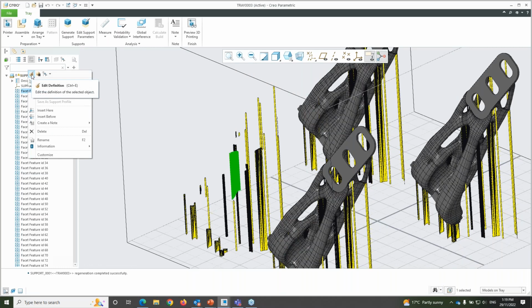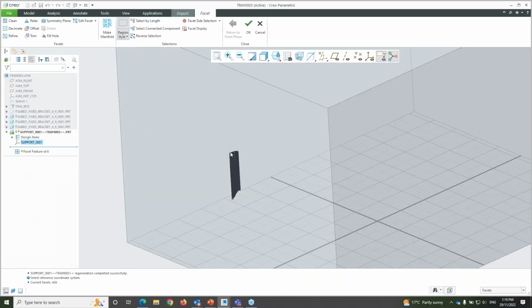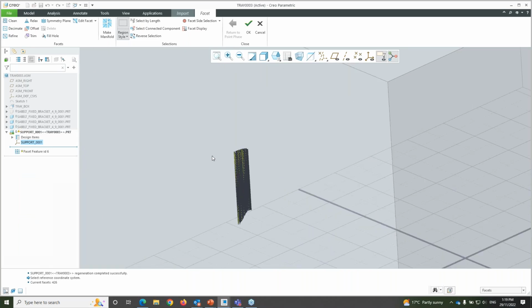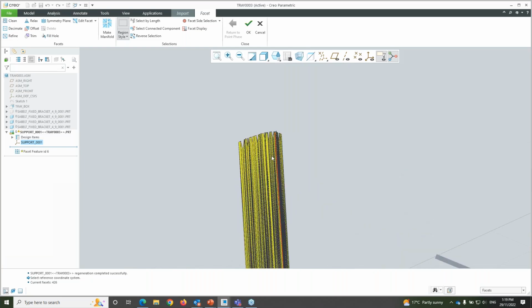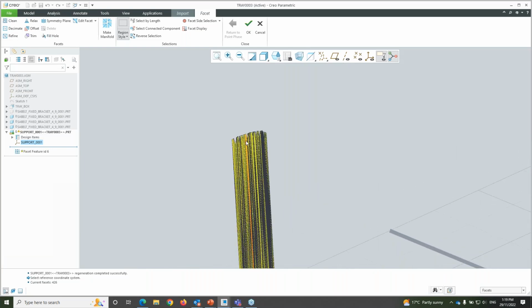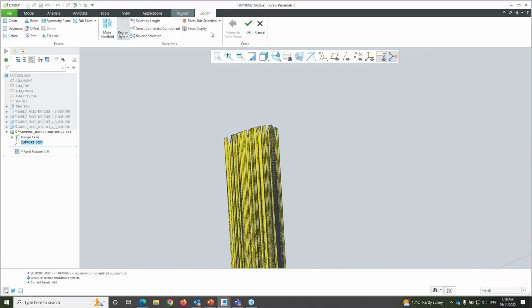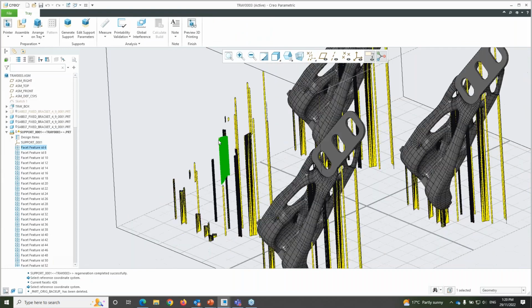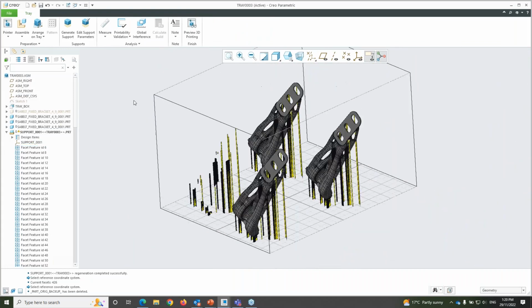And if you have a license for the Reverse Engineering extension, it is nothing but an STL manipulation tool inside Creo, inside the Rex. I have exactly the same options of the Rex to manipulate that STL data for the support. I can maybe delete a portion of that, and maybe I would like to trim that. Maybe I would like to decimate it. I can clean it. I can refine it, and you have that additional functionality also. But we need to have a Rex license for that. Okay, but PTC Creo offers that functionality, that connectivity between Rex and the support structure.